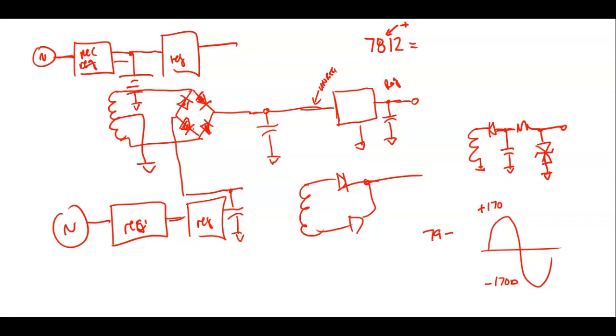First of all, you're not going to get near the spark. It would surprise me if it runs long at all. Well, if you get it started, so I was wrong. If you start it and then unplug your battery, it should run fine. But that's dangerous, guys, undoing the battery while it's running. If you take the battery off and it goes dead instantly, that means your alternator is totally dead.